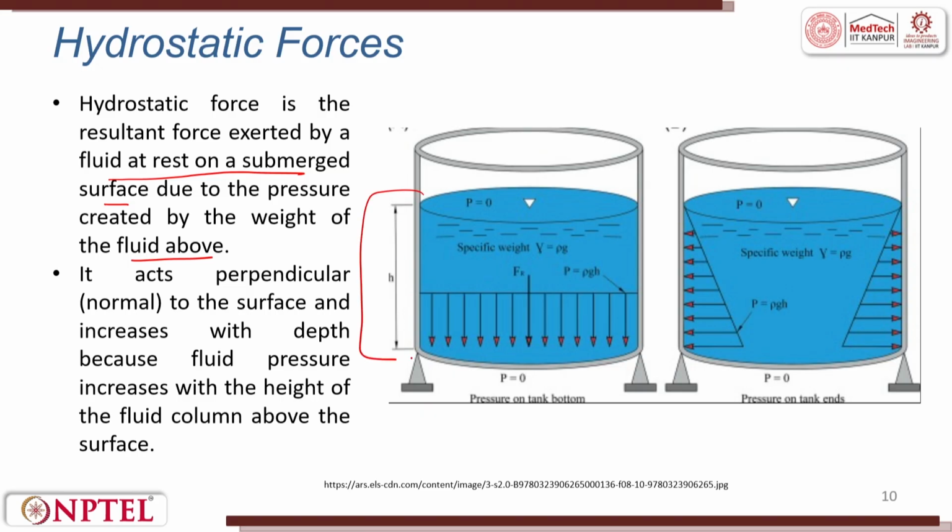So depending upon the weight of the fluid, that is the overall volume of the fluid is proportional to the weight. This height is the major thing, that is to what level the fluid height is there, that is putting pressure over it. So that is proportional to the height here. It acts perpendicular, that is normal to the surface, and increases with depth because fluid pressure increases with the height of fluid column above the surface.